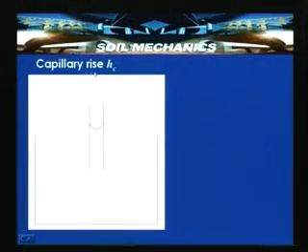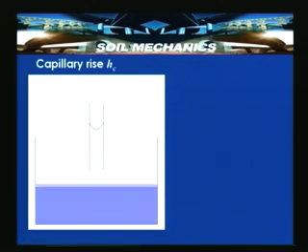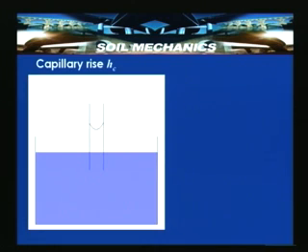Coarse grained soils can be subjected to capillary saturation only up to a certain height, whereas fine grained soils can be saturated up to greater heights, even above the water table. So, let us look into the derivation which can be obtained to calculate the capillary rise height Hc. Again, the water table in the vessel is considered.